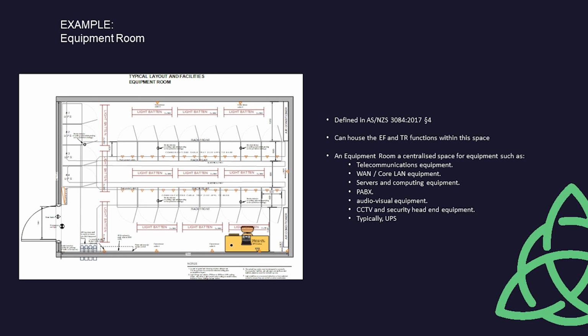The walls and ceiling within the room should be painted in a light, matte color, nominally matte white. The light, matte color must be selected to promote uniformity of lighting levels around the room to support tasks involving the correct identification of small color-coded components. The flat white paint has the ability to uniformly reflect between 75 to 85% of the light and does not create light hotspots, thus causing eye strain. The correct lighting and paint makes working on or within network equipment easier.